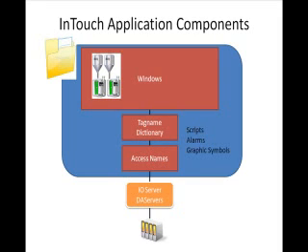InTouch uses the access name feature to make a connection to the PLC and serve PLC data to tags defined in the tag name dictionary. These tags are visualized on windows via InTouch graphics. They're also manipulated and monitored with other features like scripts and alarms. This is the essence of InTouch, and obviously there are many details I'm leaving out for another day in another video. Let's have a look at the software itself, and I'll show you how to get started.